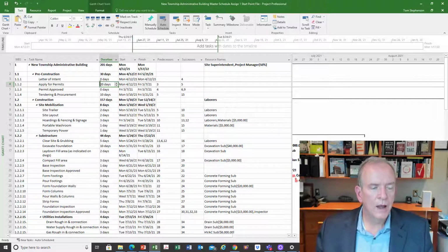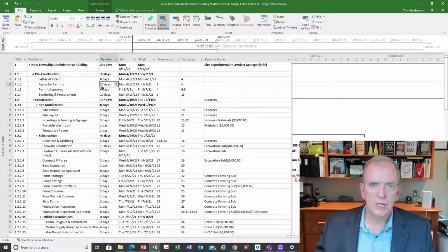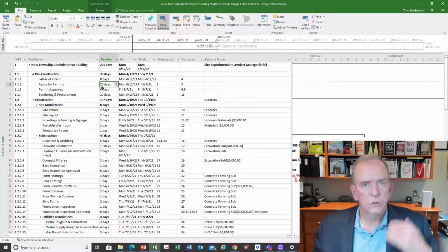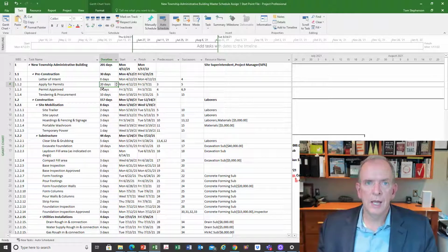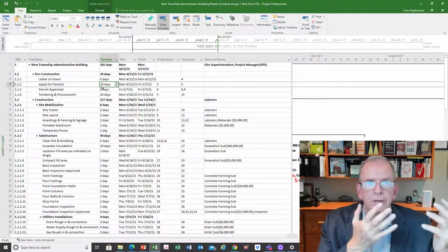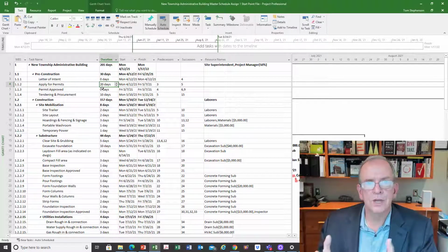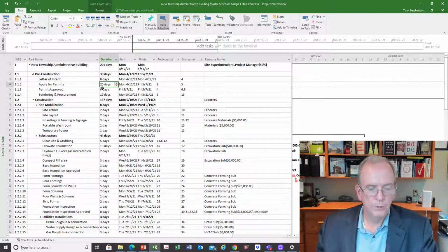What's my time frame for permits, right? This is 20 days. It could be 10 months. It could be 2 years, if I've got zoning changes and other things that I have to do. So I can take this step by step by step, and I can start to pull together a project plan. And if I start to do that and sequence and procure the work, then I can put a timeline on it and develop a schedule. But I need to have the drawings, I need to have the specifications and documents, because how else am I going to do this? So this is the fundamental basis for doing